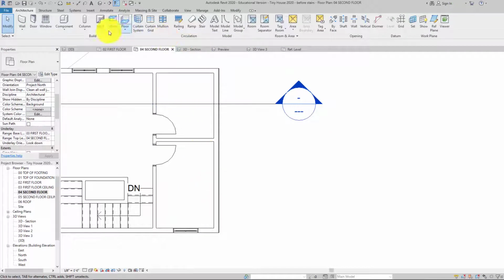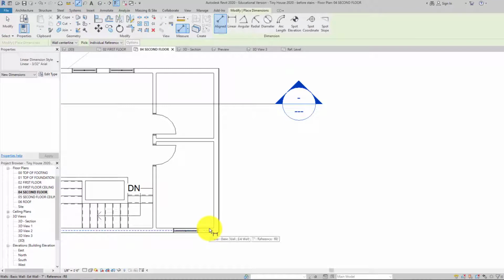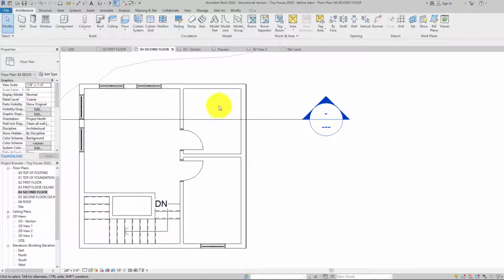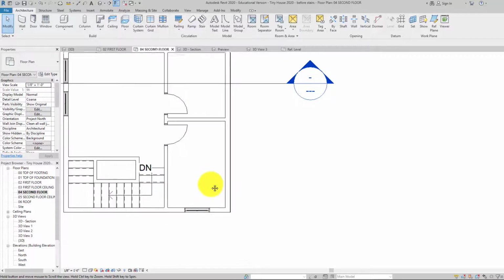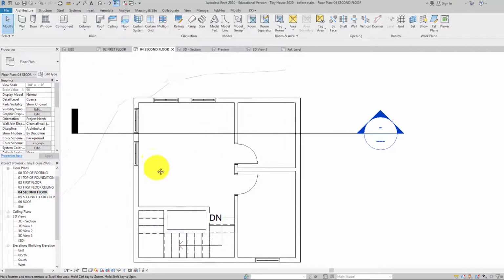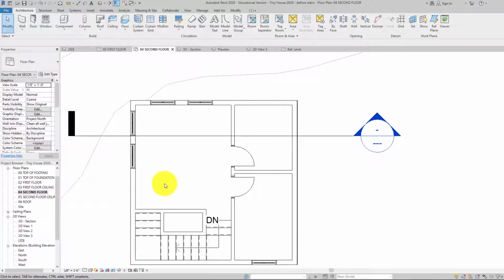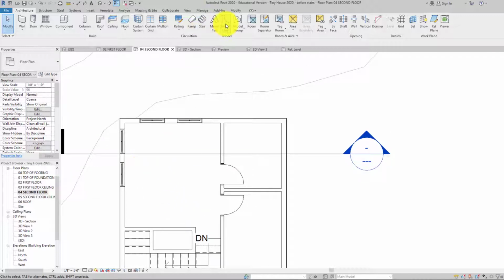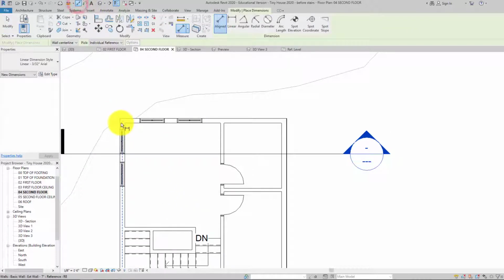That looks pretty good. Let's see how big this room actually is. Let's grab an align dimension, hit tab. 10 feet 6, perfect. What do we got here? 6'11". So this is a pretty good walk-in closet, and that's a pretty good bathroom. So really, this is all basically set out. Now let's go ahead and dimension the outside edges while we are here.